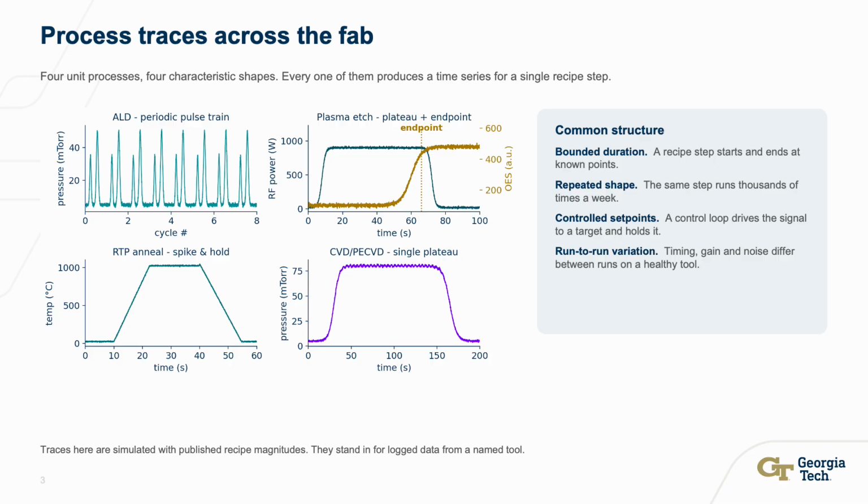Bottom right is CVD or PECVD. Pressure rises to a set point, holds for the deposition, and comes back down. One plateau. 4 different processes, 4 different shapes. What they have in common is listed on the right.